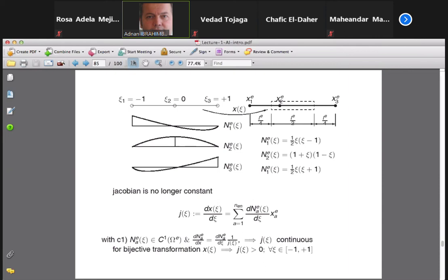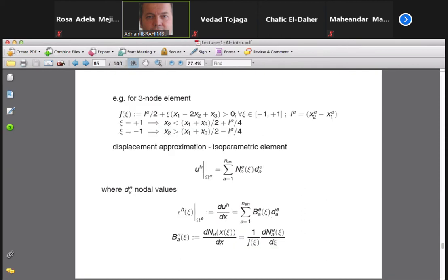So it was equally complicated, if not more, to provide some nice finite element mesh for a complicated problem than it is to solve the problem, at least in terms of the practical tools. That's why these things are important to tell, to know the reason why you do it. So imagine now when we compute this high order approximation, displacement is obviously a quadratic field, strain will be a linear field, and of course it becomes quite tricky to compute these type of things with the different shape functions, and we'll see this is done by numerical integration.